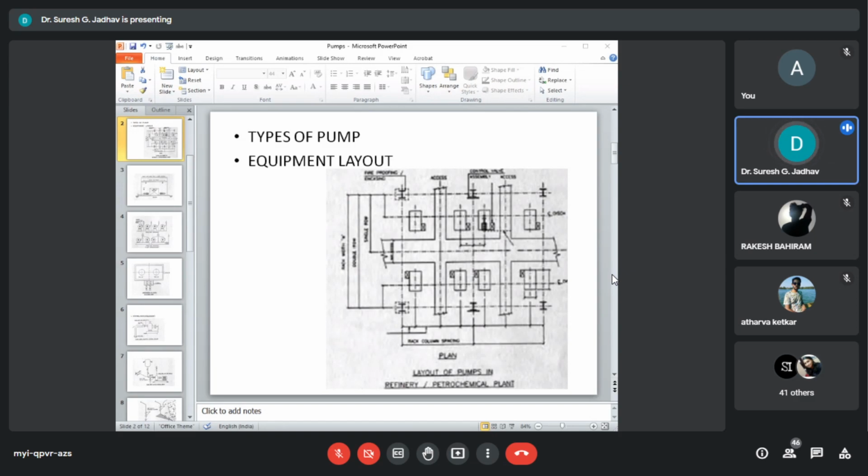The positive displacement pump can be a rotary or a reciprocating type. The rotary pump works with forced volume displacement and can deliver a constant pulsation-free flow against higher head than centrifugal pumps. The layout and piping design do not differ from that of centrifugal pumps. Reciprocating pumps are used where very high head is needed for low flow.